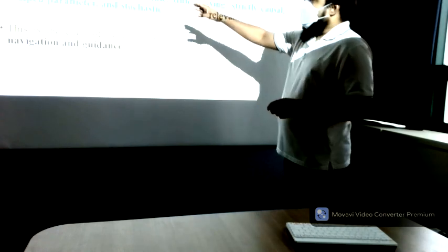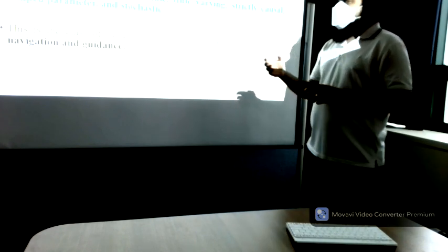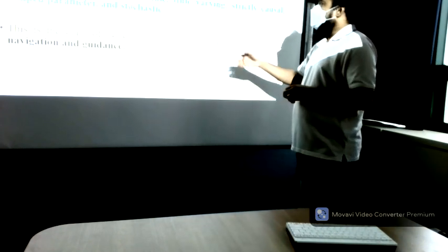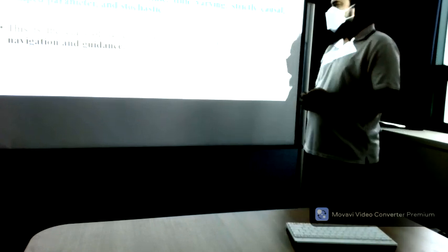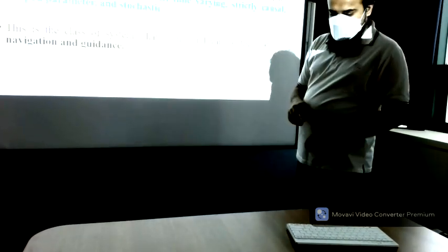So in view of the preceding lectures, the systems considered in this GNC course are mostly linear, dynamic, time varying, strictly causal, lumped parameter, and stochastic. And this is the class of system that is the most relevant to the study of navigation and guidance.